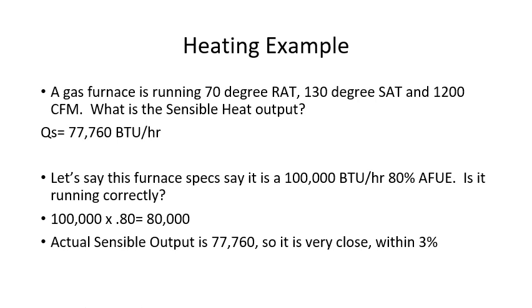Why may it be a little bit off? Why aren't we calculating exactly 80,000 BTUs per hour? Well, there are a few factors in play. For one thing, the utility company may have altered the fuel mixture a little bit, so that could be in play. The other factor is elevation. If we're really close to sea level or we're at a higher elevation, that can affect not only the heat content of natural gas, but also the airflow.